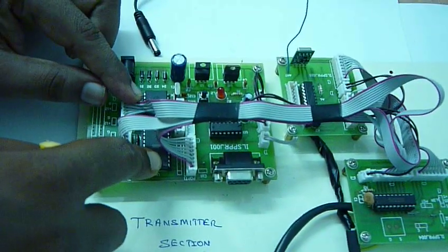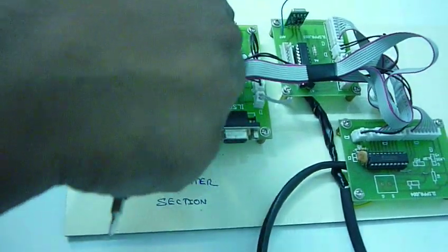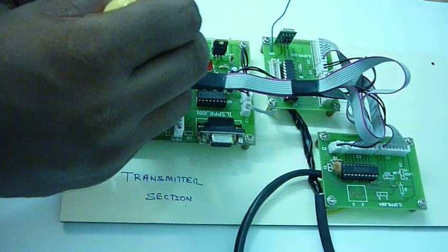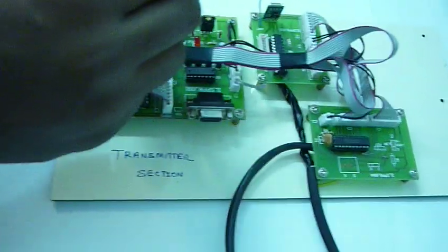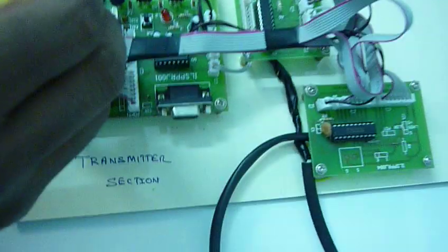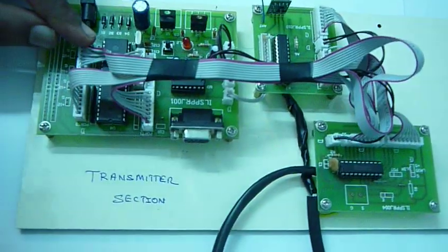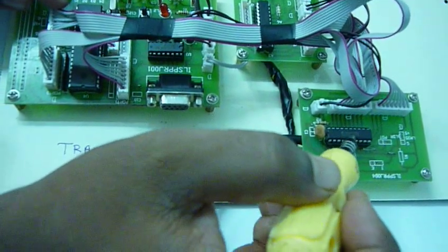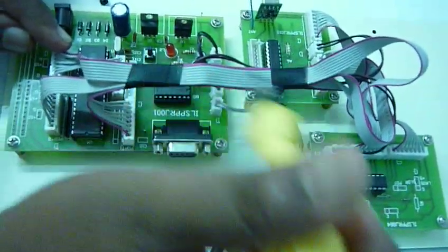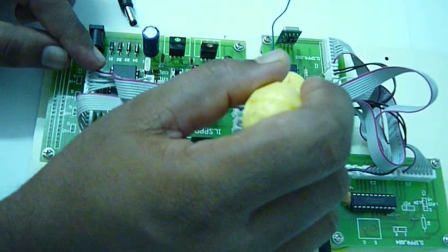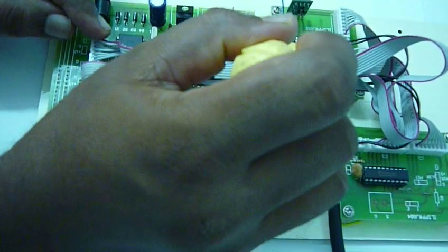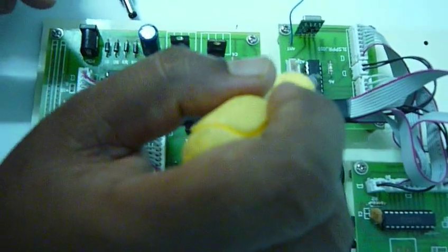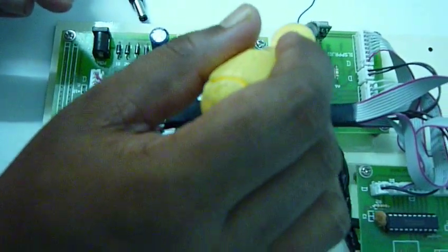And for the operation of the microcontroller, we need a reset circuit. This capacitor, along with this resistor and this push button, acts as a reset circuit. This is a crystal oscillator which supplies clock pulses to this microcontroller. Okay. Here is the ADC. This ADC is the 0804, which converts the analog data into digital. The data that is coming to the microcontroller is in turn given to the wireless encoder. This wireless encoder is the Holtek HT640. This IC is used to communicate the data via the transmitter section.